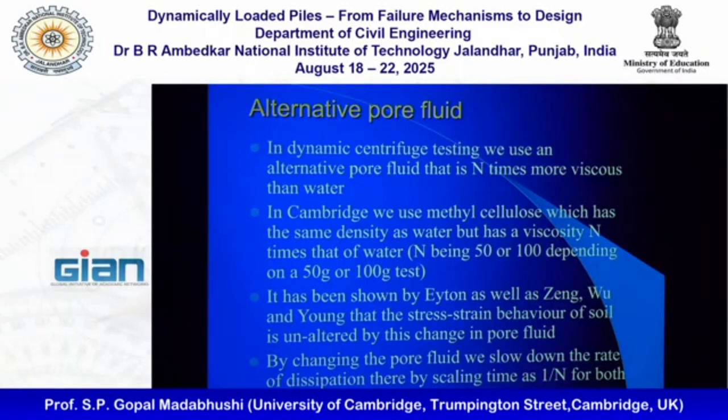They did cyclic triaxial tests by saturating the sand samples with water and also methyl cellulose at different viscosities. And what they have shown is that the stress-strain behavior remains unaltered even if you use viscous fluid in it. Okay, so this is the verification.